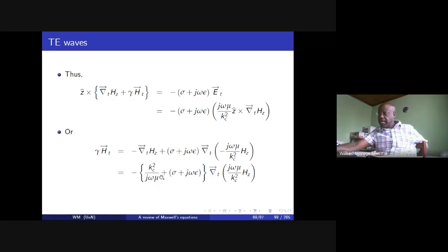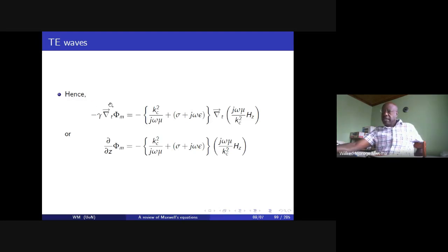Again, this would be an inductive impedance down here at the bottom, and that is a conductance or an admittance. And therefore, all we are saying is that this is a parallel combination of an inductive impedance and a lossy capacitance, a capacitive admittance. So this will be a parallel combination. So we can therefore have that the minus gamma of that is equal to that, and therefore we get left with that equation, which is similar to the other one, and we make the interpretation as follows.